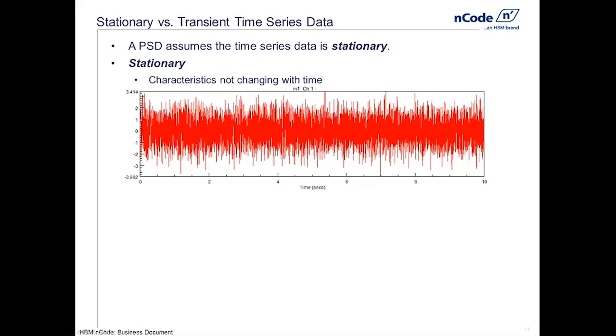That means if the PSD is showing us the average amplitude over time, the amplitude has a pretty consistent average over time in the time domain. So therefore, I have a better feeling about the amplitudes that are being returned in the PSD. The PSD has a pretty reasonable understanding, through statistical averaging, of what is represented in this process.